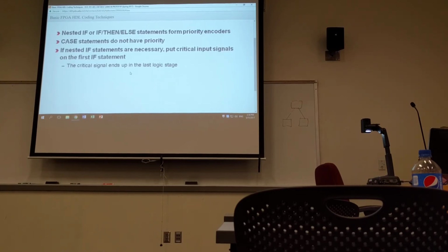If the last example was constructed with 4 LUTs, it would require only 2 logic levels. Recall that the function had 9 inputs, which would require 2 LUTs in series and a total of 3 LUTs. So see if you can make that work and replicate what we expected and how the difference would come by using a case statement.